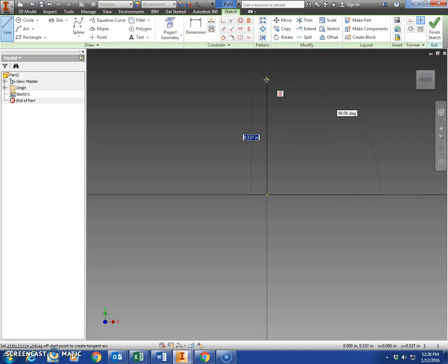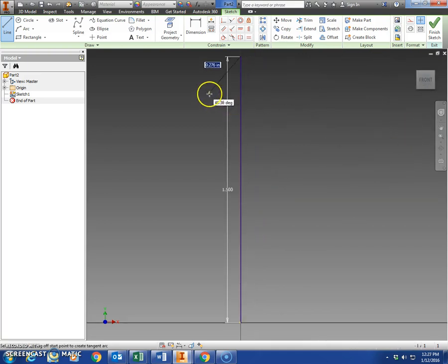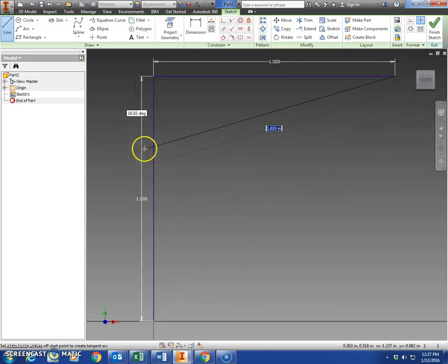Okay, and we're going to type in this box over here, 1.5. Enter. That'll bring us back here to the beginning. Okay, the magnifying glass kind of zoom out there, and then we're going to draw a line straight out here. Make sure that it's 90 degrees down there, and then this is also going to be 1.5 inches. Enter. So we've got two lines now, a line going up the y-axis and a line 1.5 inches going out. Now we're going to go down, straight down here, 0.75 or 3/4 of an inch. Hit enter.